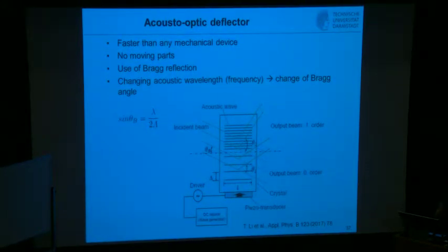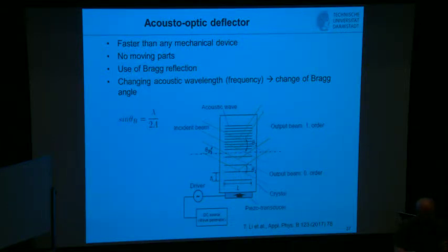And we have used that recently in looking into engines, where we have performed multiple sheet PIV. Instead of having tomographic PIV limited in depth, 4 to 8 millimeters, in engines you're typically interested in larger distances.